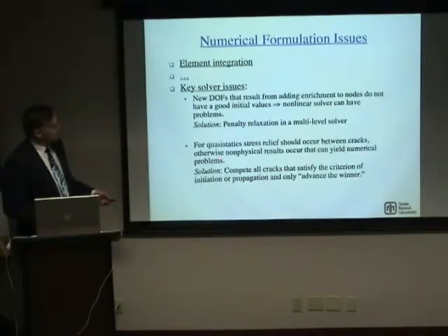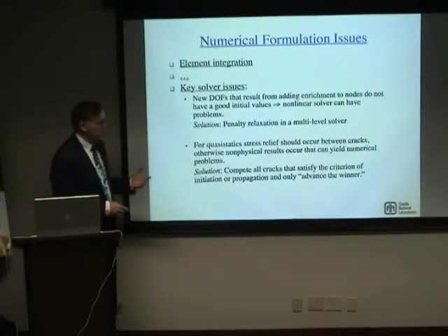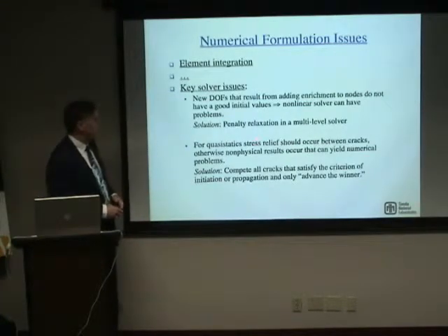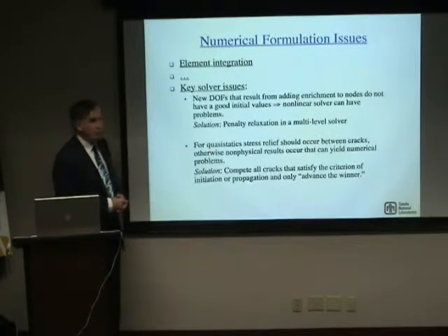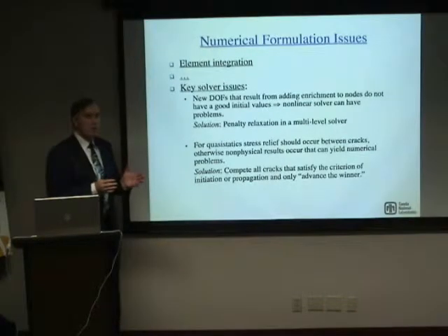Now the other item that I mentioned here is that it seems to be physical at first, but it's not purely physical. Let me put it this way: it has an effect on the numerics, and that is for quasi-statics, stress relief should occur between the cracks. That is, if we're doing a problem at relatively slow loading, the unloading that occurs due to one crack opening should affect whether another crack develops or not.